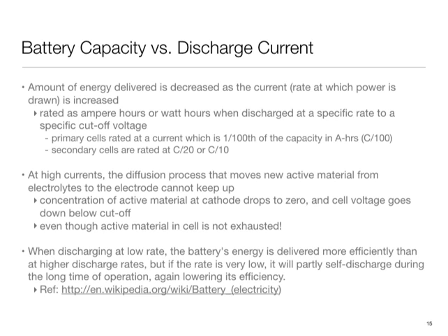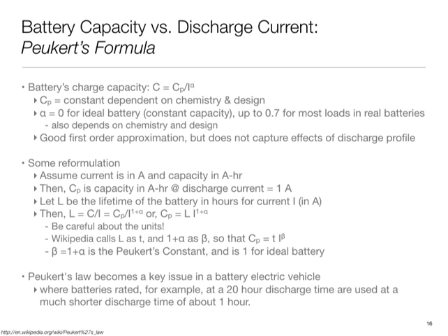Well, the problem is batteries also discharge. So that complicates life, right? I mean, if you use the battery over a longer time, you're taking a hit on that side. This is akin to the static power consumption. There is a static power dissipation from the battery. So that balance needs to be thought of as well. So just slowing down things to the extreme is not necessarily the answer either. Depending upon the specific system, one has to account for these things.